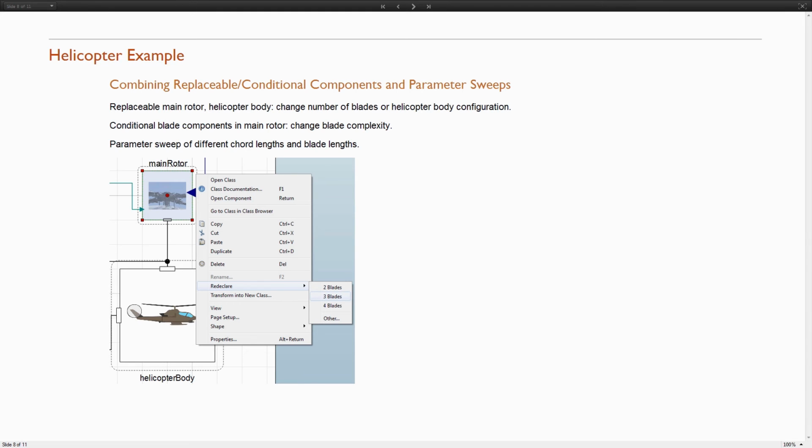If you have a lot of these points, a lot of blade elements, it will be a really exact description of reality, or at least the physics described. If you choose fewer of these points, we will get a less physically accurate model, but it will be faster to calculate. So that's a really handy way to change the complexity of the model.